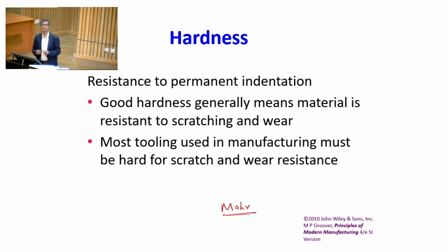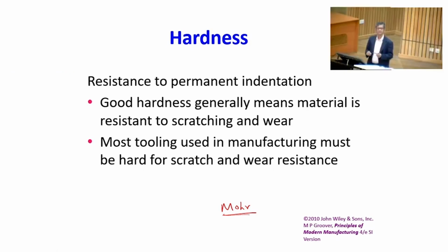Well, in most cases you may not be able to measure the tensile properties of a material because of sample size limitation, or because of accessibility to a tensile testing machine. So, in those cases we use hardness as a parameter to obtain the mechanical properties, mostly the strength, right. As you know, hardness is nothing but resistance to permanent indentation or deformation, okay.